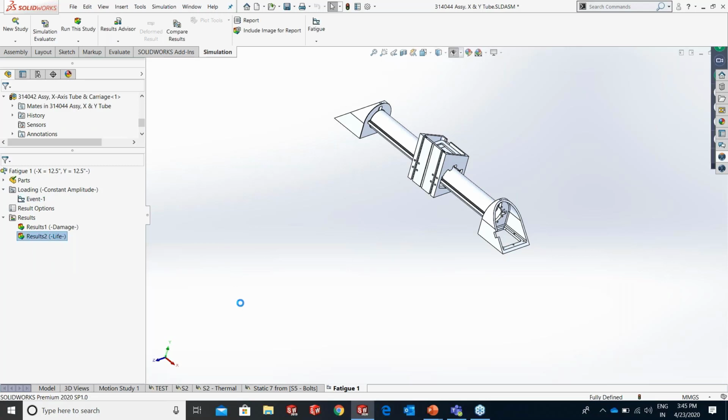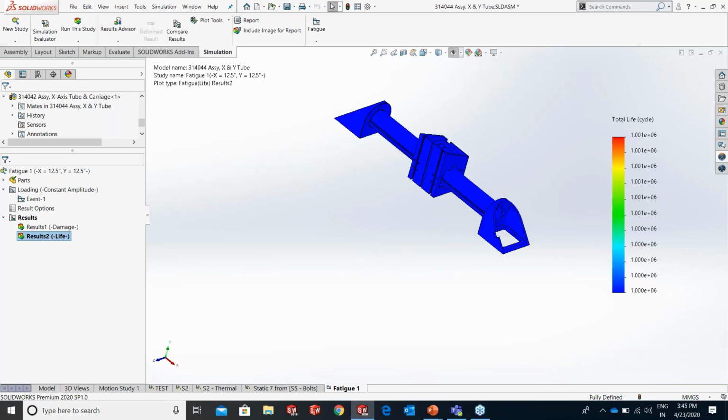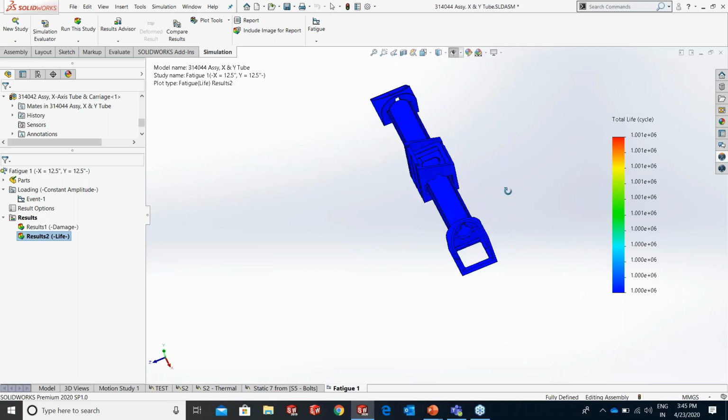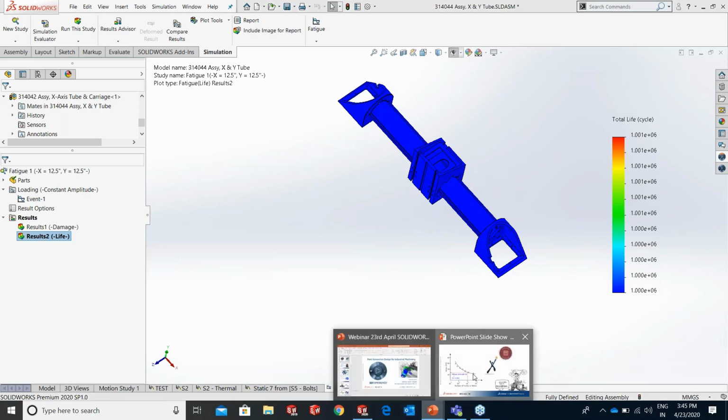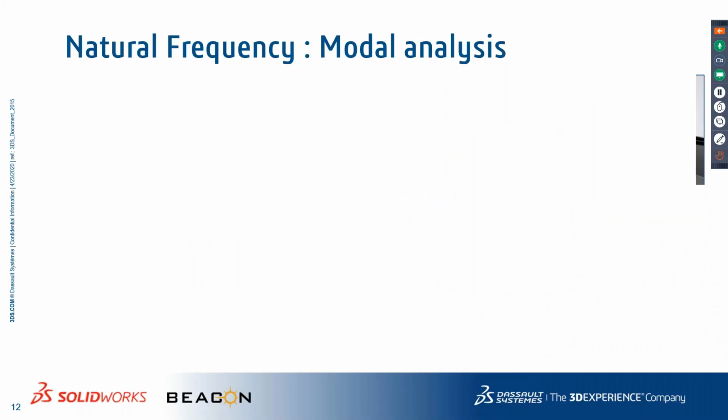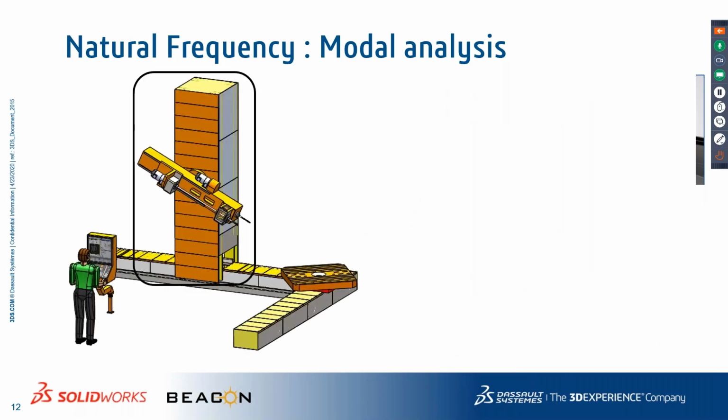From this, you can basically prepare the service manuals. Let us say, for example, after so many cycles of load, the crack is going to initiate on this member, and after these many cycles, we can take some preventive actions to prevent the catastrophic failure of those structures.